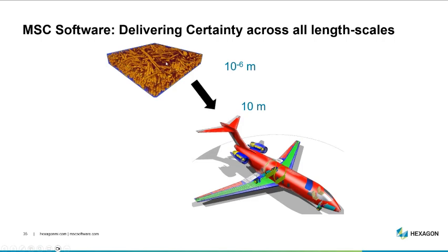Let's say we've got some kind of a composite. There's probably two cases that are relatively common. The one would be fiber layups, but the other one is, what about fiber injected or injection molding? In that case, we've got these short fibers, typically with some kind of an interesting distribution, and I need to know what the stiffness contribution of that would be and the strength. While Nastran's great at many things, it can't really do this well. So there's a different product from the same group of products, MSC Digimat, which can microscopically model this and map that into equivalent properties that we can use in Nastran.